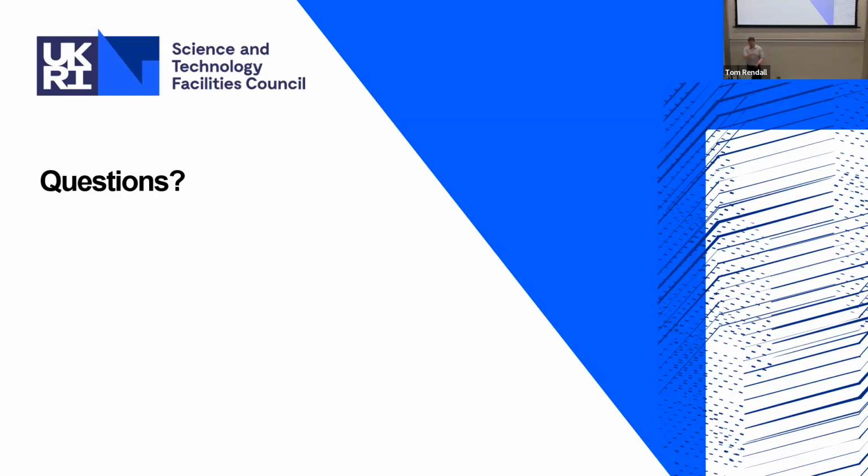It's an unbelievably scalable method for its specific use case. At the moment, the method we have only really supports one parcel equal to one molecule. It's not actually a huge extension. It's something that's on the list. It's been on the list for years. The more difficult thing is how do you couple MD to CFD? DSMC to CFD is fairly obvious in how you do it.